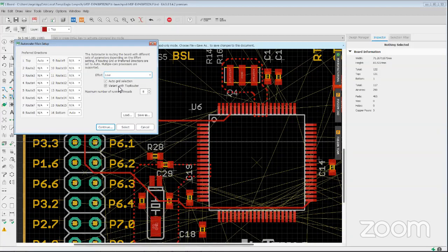In general, the result tends to be aesthetically a little bit nicer. It's a very subjective thing, but that's been my experience. Additionally, it tends to produce fewer vias. The downside is that because it is an intelligent algorithm, it does take considerably more time to run. So if you have a large design, it can take a good while to run. So if you need to get something in a hurry, it's usually a good idea to uncheck this, because the top router is going to take substantially more time to run than the old algorithm. But we'll leave it here for this example.